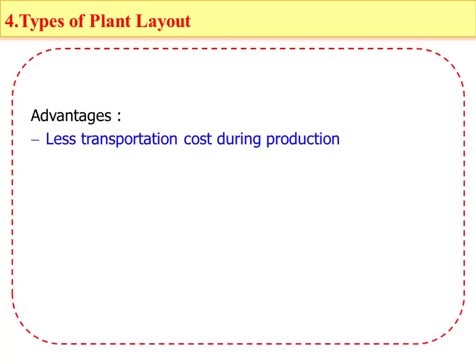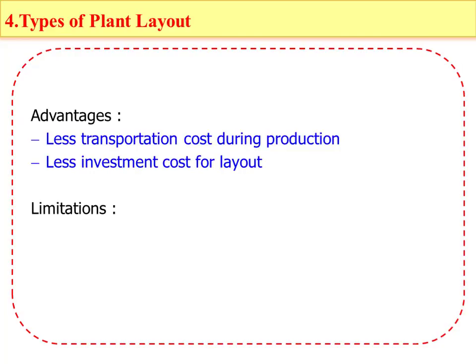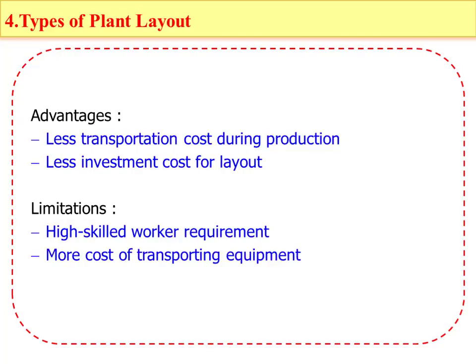And the advantage of this layout is that you have less transportation cost during production because it is working in one position, and less investment cost for layout. The limitation is that it requires workers with high skill, and the cost of transporting equipment is more.